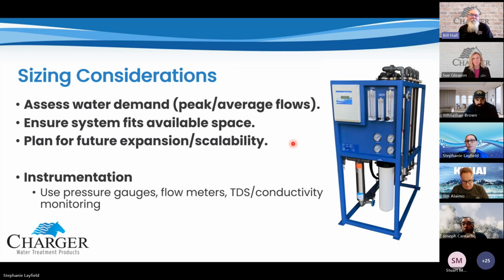Generally, you can tell by the pump. Take a look at the pump where it feeds. Does it feed just one membrane, or is it split and feeding two membranes or more at the same time? If so, that would be a parallel type system.